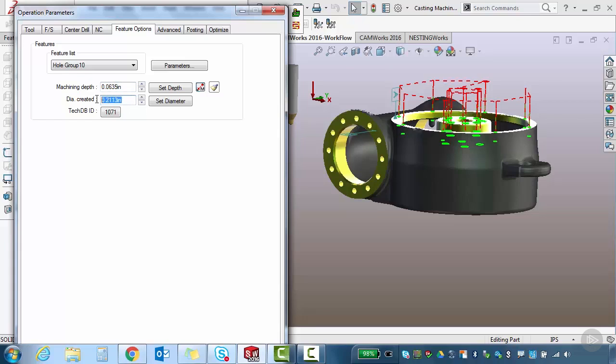You also have the ability to change the diameter. So if you wanted it to make a bigger diameter hole than what it's currently going to do at a 1/16 inch deep, you can tell it I want it to be 250, and if I hit tab and hit set diameter, you'll notice to make a 1/4 inch diameter off of the tip of that tool, it's going to require it to be 75 thousandths deep, which is a pretty cool feature without having to math it all out. You can say, well, I just want to be able to countersink to a 1/4 inch diameter.